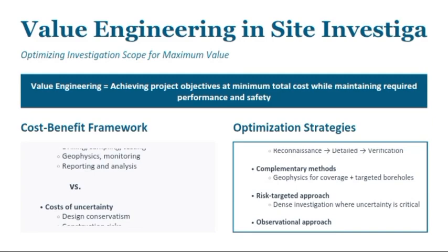So the thing is this, like I said, it's not cutting corners. Instead, it means optimizing investigations intelligently. For example, instead of drilling many unnecessary boreholes in low risk areas, resources may be concentrated in critical foundation zones, areas with uncertain geology, or environmentally sensitive regions.